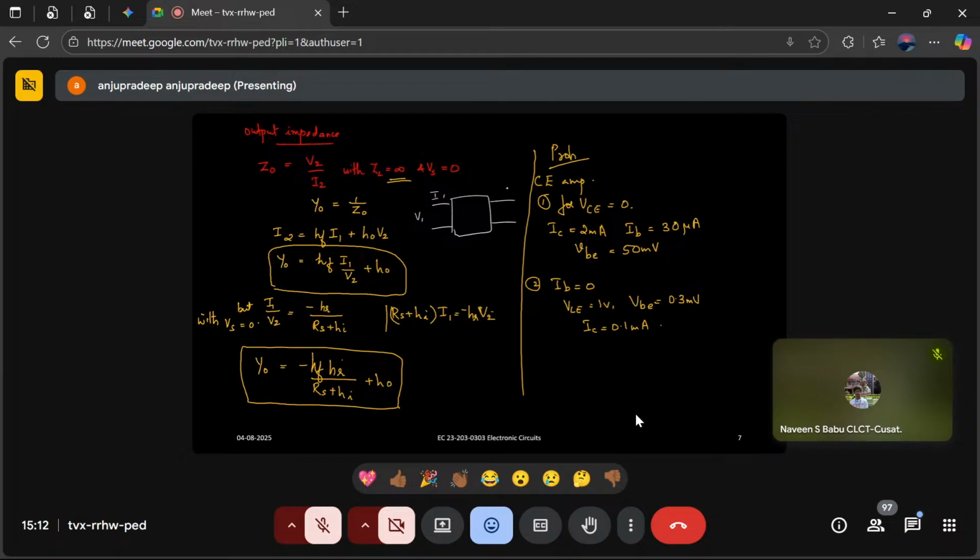What we are interested is you want to find what is the impedance at this port. So what you have to do, you have to make this 0. That means you consider this is not there. You are not applying any voltage there. You apply some voltage here and you measure what is the current flowing into the circuit. So you don't want anything after this also. That is why ZL is equal to infinity and Vs is equal to 0. So the simple rule is, wherever you want to measure impedance, you apply a voltage at that point and measure current flowing into the circuit.